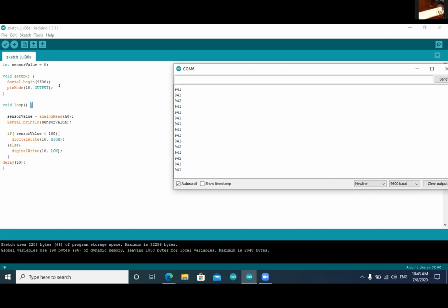Basically, this one. Okay, can you walk us through your wires? This one is the wire that connects from the ground bus to the photoresistor. Then the resistor, that's 1,000, goes through here, and this wire connects it to the plus. And the one that is listening, on the A0, it connects to the point where the photoresistor and resistor hold hands, right? Yes, it connects right. Bring it closer a little bit. Let me see. Yeah, there. This one.